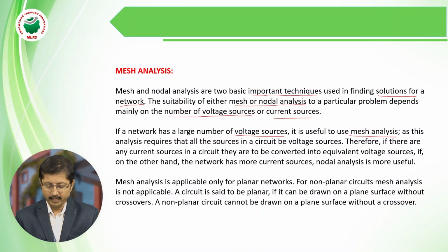In the same way, if there are many current sources in a circuit, then we convert them into voltage sources and after that we use mesh analysis. Mesh analysis requires all the sources in a circuit to be voltage sources.